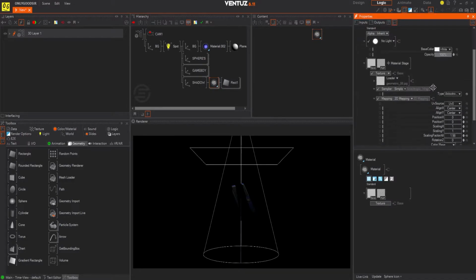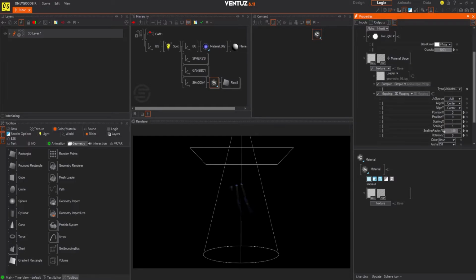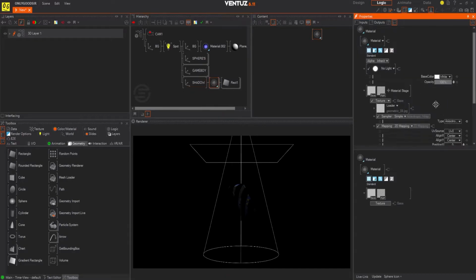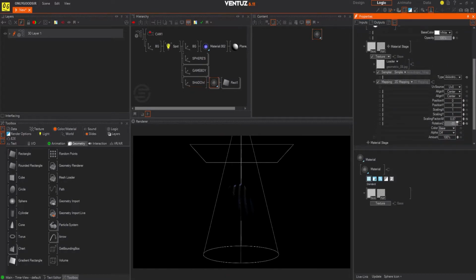And if I adjust the UV mapping on the scale, as you can see, the tighter I bring it, you can see the texture there, and it's starting to look really nice. Now of course I can rotate this. The reason I'm editing the UV is I can choose to move the position of this plane up and down, which also has an effect on the shadows, but it's easier for me to tweak this to get the look I want. I can stretch this out or tweak this texture, and it will still affect the shadows,